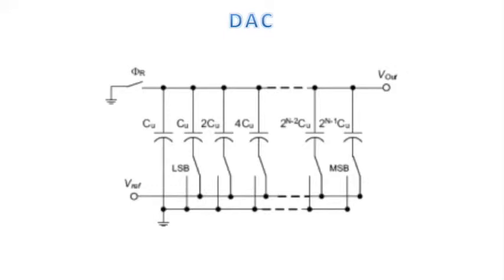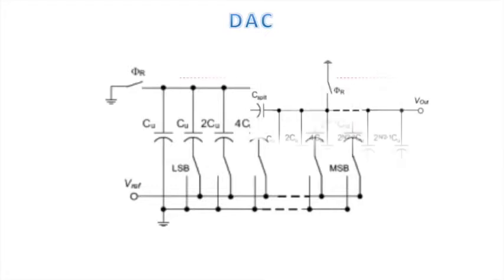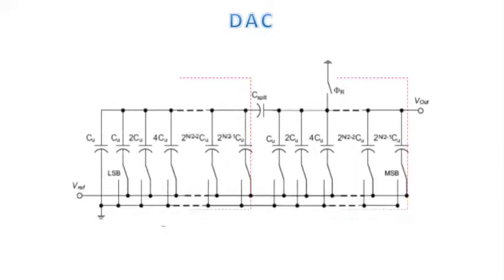For the digital to analog converter, a binary weighted capacitor array is chosen. Each capacitor is switched between reference voltage and ground depending on the input code value. To further modify the design, a two-stage approach is implemented. The array is divided into two parts plus a coupling capacitor. This method will decrease the total capacitance and therefore decrease the power consumption and area.